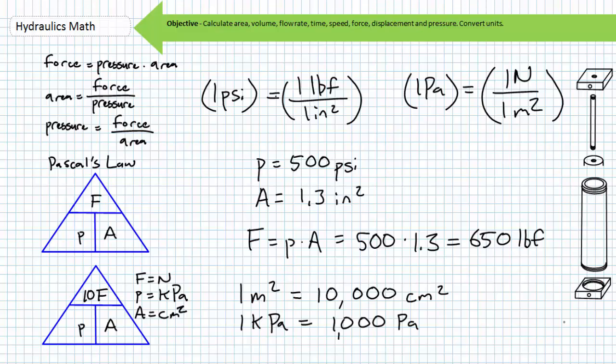Given this merry-go-round of conversion could get confusing at times, I like to think of the 3-variable relationship between force, pressure, and area when expressed in the quasi-SI metric system units of newtons, kilopascals, and square centimeters as requiring an extra 10 in the force position. This accounts for any conversions up or down, and the 10 can be repositioned as needed.